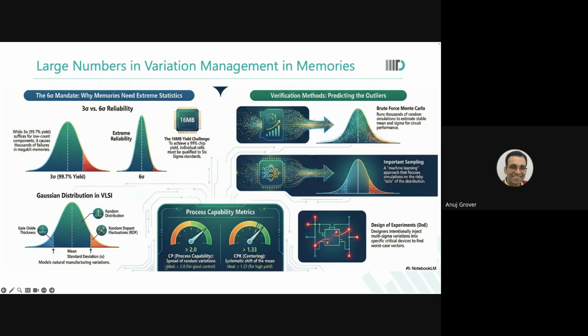If we assume these functions are Gaussian, there are two variables we could have, mu and sigma. One of these two characteristics, CPK, looks at the probability of movement of the mean away from the target. The other looks at what is happening to the sigma, how big the sigma is, and whether you will be within the target specifications of the process or not.